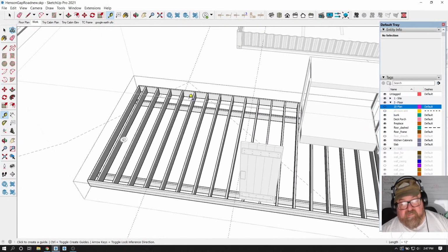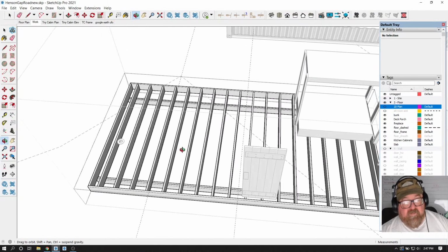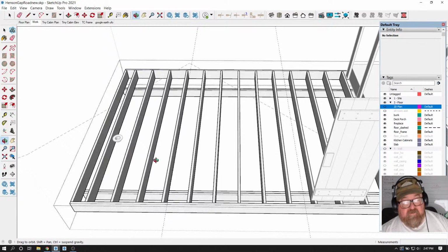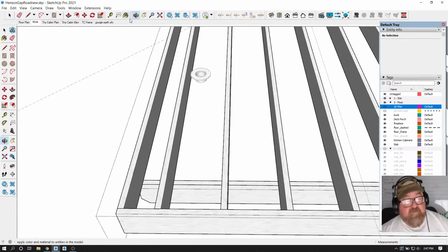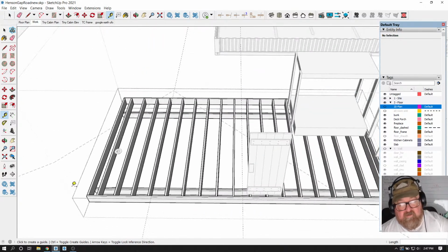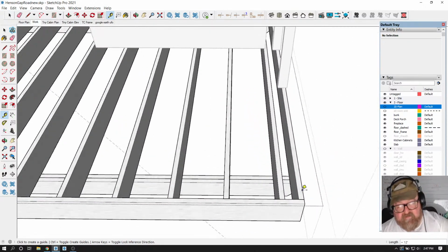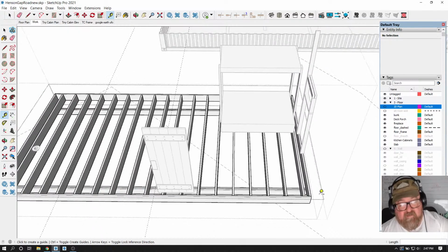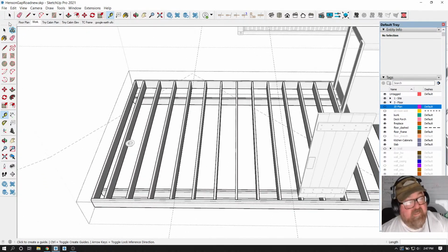The point I'm trying to make there is that if you're going to do something like this, you want to lay out your joist. You see how there's a space here that's not 16? If you go from the end, it would typically be 15 1/4 from one end or the other to make it 16 inches on center. Well, don't worry about that. What you want to worry about is your plumbing layout, okay?